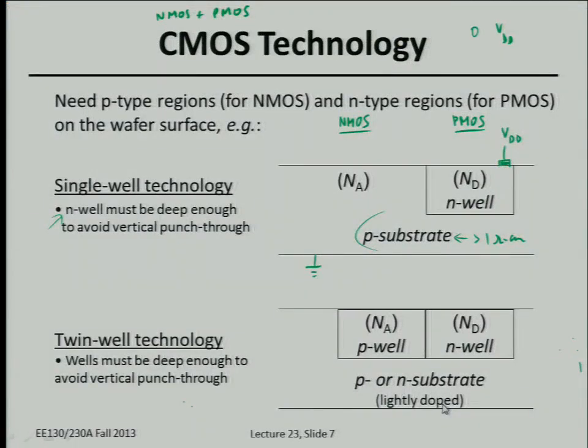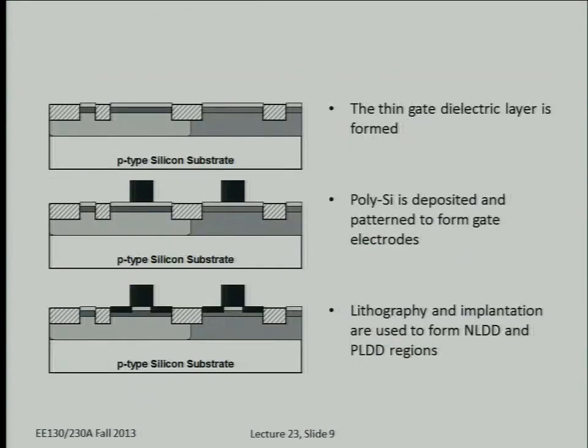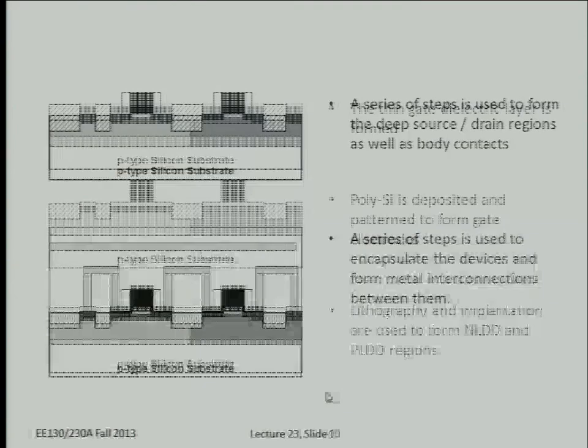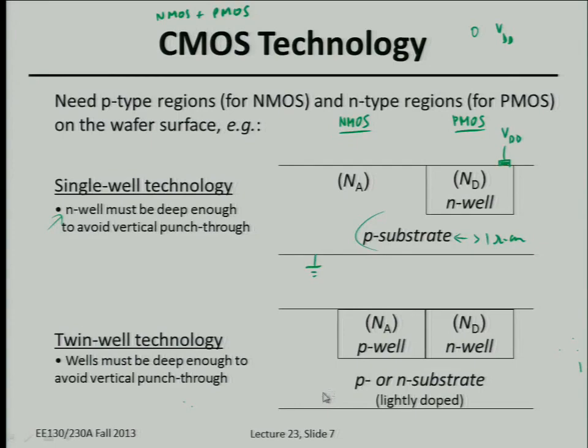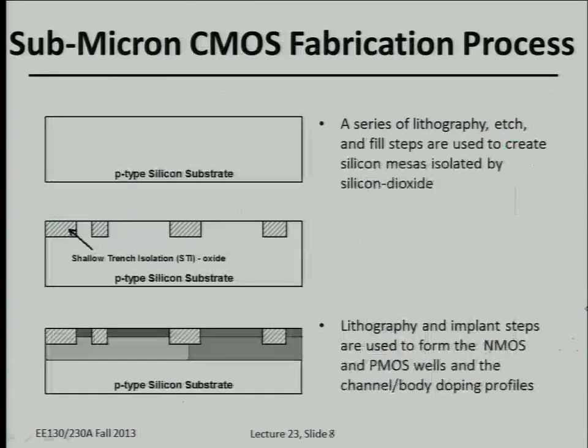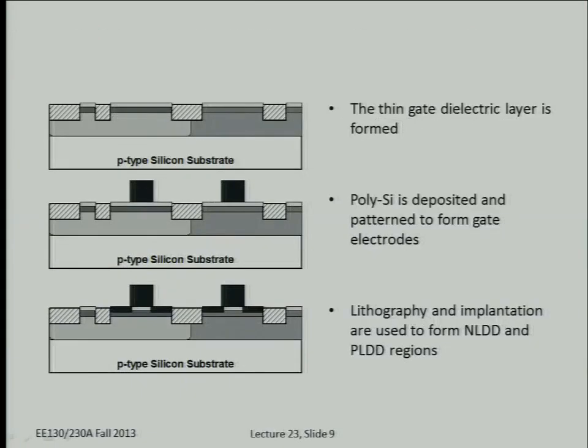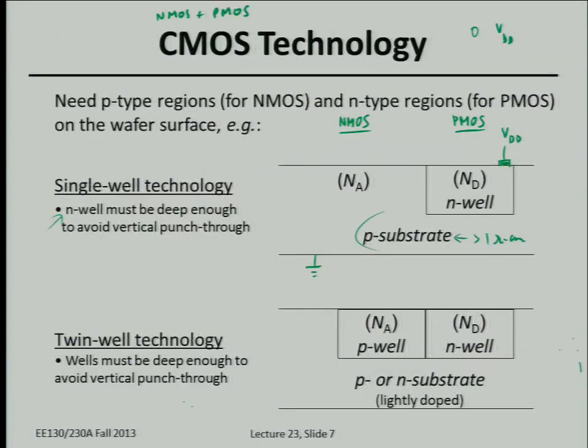Yeah, because there's really no reason to. The NMOS and PMOS transistors are usually laid out side by side, so there's no reason to form separate wells for them. I mean, separate wells for PMOS transistors. You just want a separate well for PMOS versus NMOS, but not PMOS versus PMOS. And they're all biased at ground, or I mean, this N well here is biased at VDD for many transistors, and then the P well or the P-type substrate is grounded for many transistors.